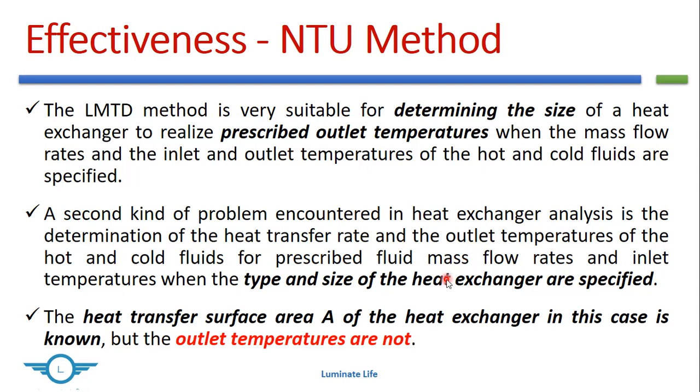The mass flow rates will be given and the inlet temperatures will be given. Additional to this, we might have already selected a type as well as size of heat exchanger. So here we will have the heat transfer surface area A. We will know this, but the outlet temperatures are not at all known.